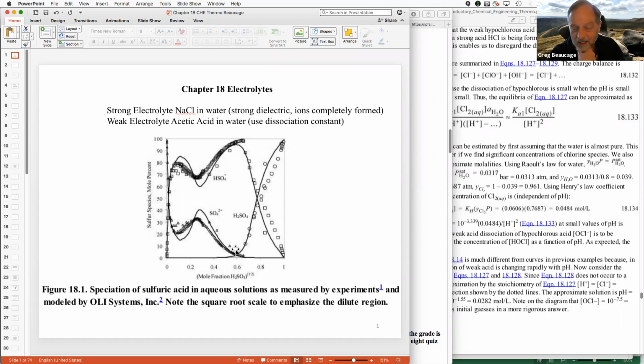For instance, a lot of these are high temperature, like molten sodium chloride would be an ionic fluid. Basically, when they do concentrated solar, they have a field of mirrors and shine it on a spot, and the temperature gets to 4,000 degrees. So they need a heat transfer fluid, and they use an ionic fluid. You use something like a salt, like sodium chloride, and it melts. They make molten sodium chloride that runs through insulated pipes down to a heat exchanger that makes steam, and then they make electricity with the steam from that.